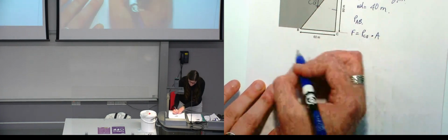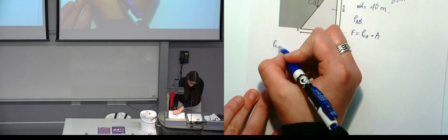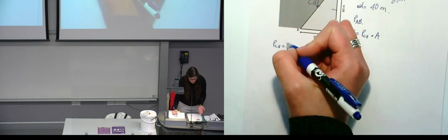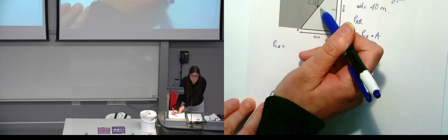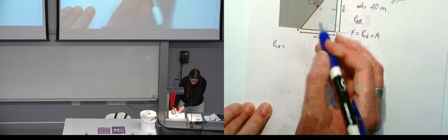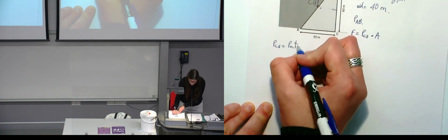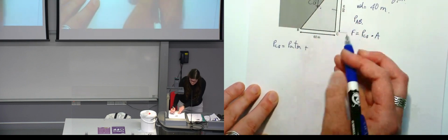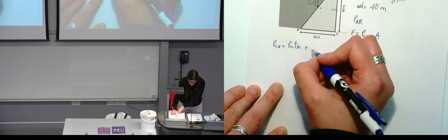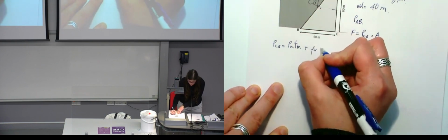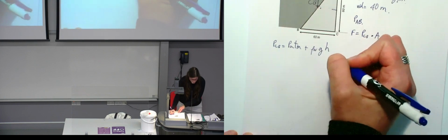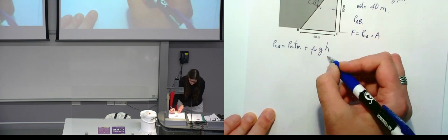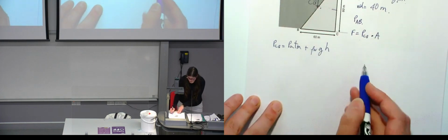So then the pressure at the center of gravity is like we were doing before. What's on top of this center of gravity? We have the atmospheric pressure, and then all the pressure of the water on top of the dam. And this pressure is rho g h. And we know all these values.